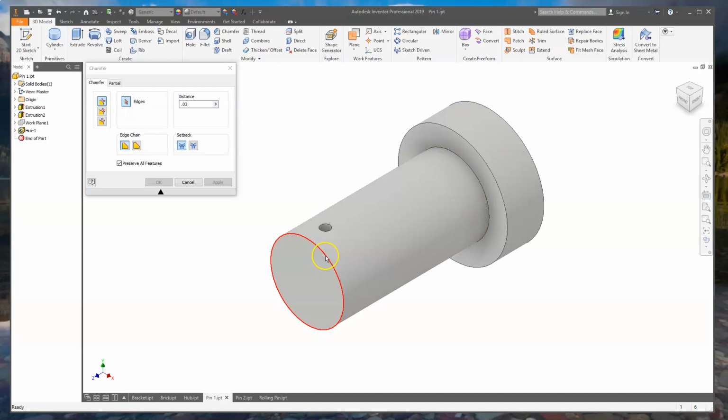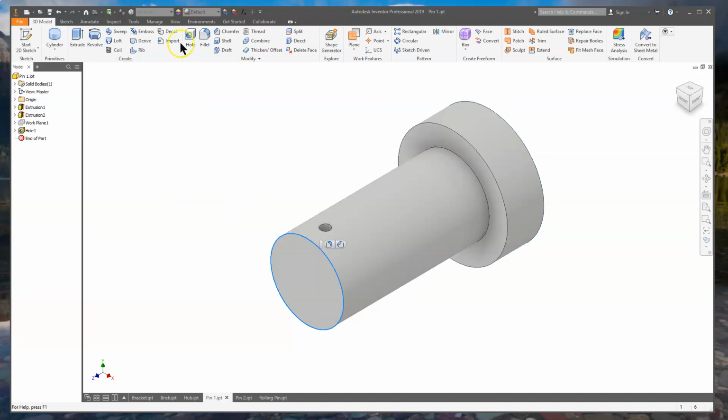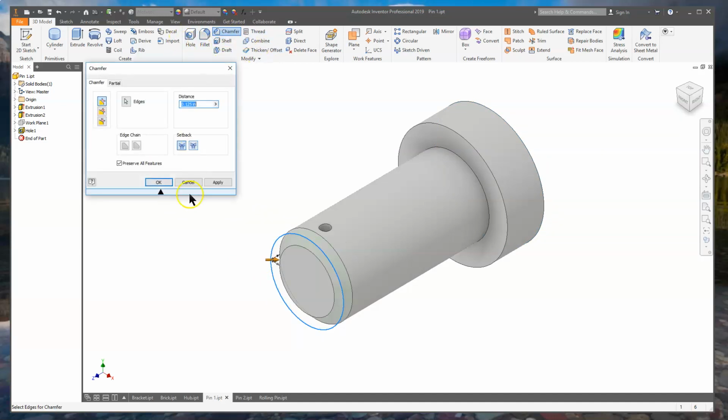Sure, on this pin, I'm going to go here, put one there. I'll put a chamfer there and a chamfer there. I did all three places at the same time, right? Whoops. That's not liking that again for some reason. All right, let me go here. Maybe I have one cancel. What's going on? Chamfer. Oh, here's why. It's too big. 0.03. There we go.